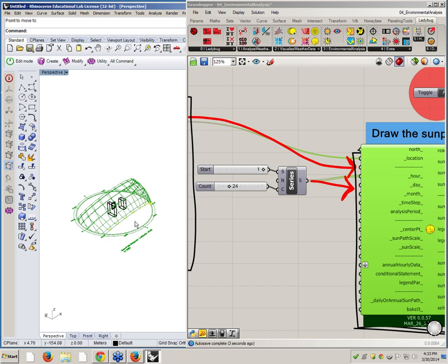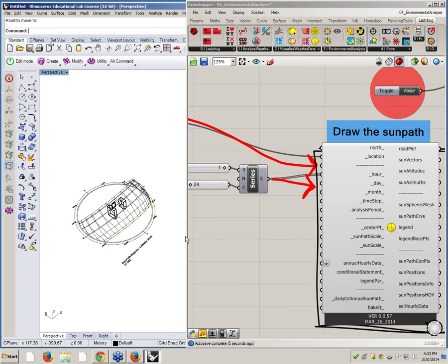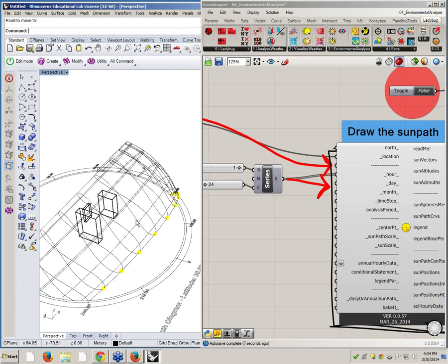Sunlight average is a standard, more of an urban design standard than architecture. And in many areas it's part of a code. For example, it depends on where the code is, but they say if you have a residential building, for the bedrooms, it should have 2 hours of sunlight during the 21st of December, which means during 21st of December, you should see at least two hours of sun.